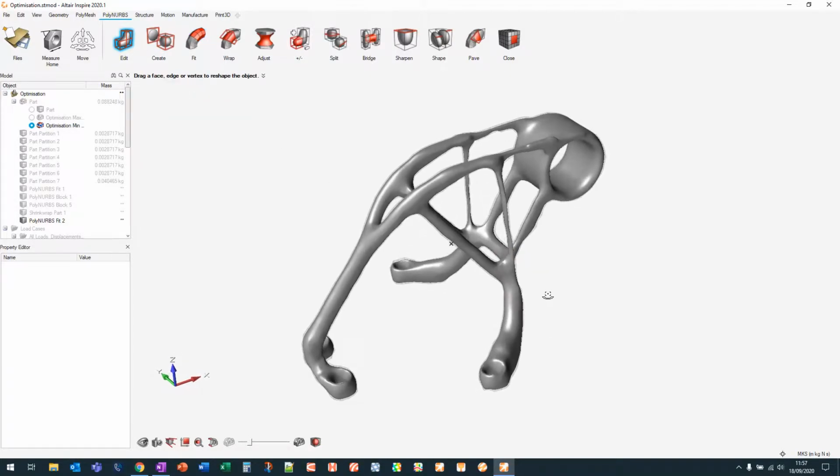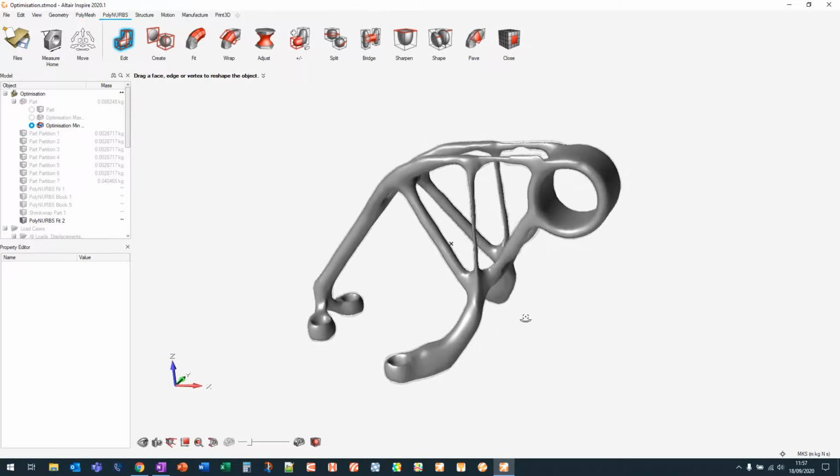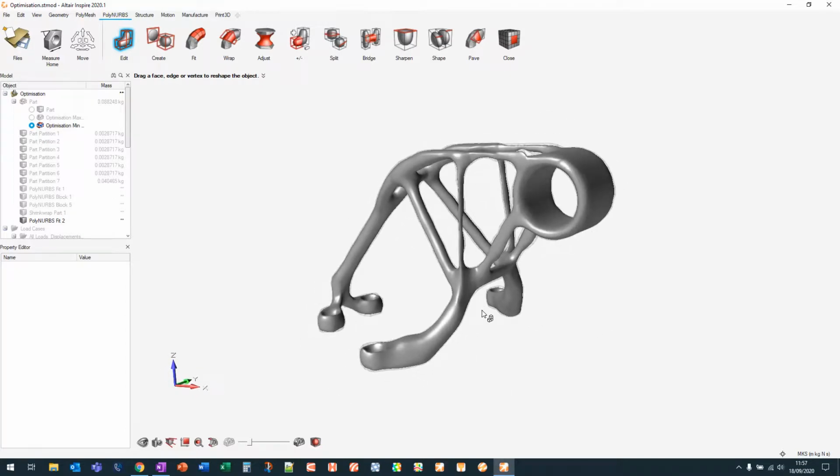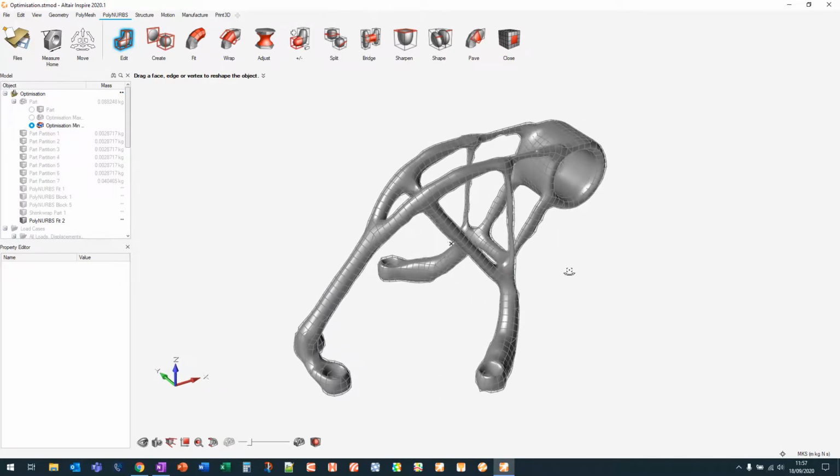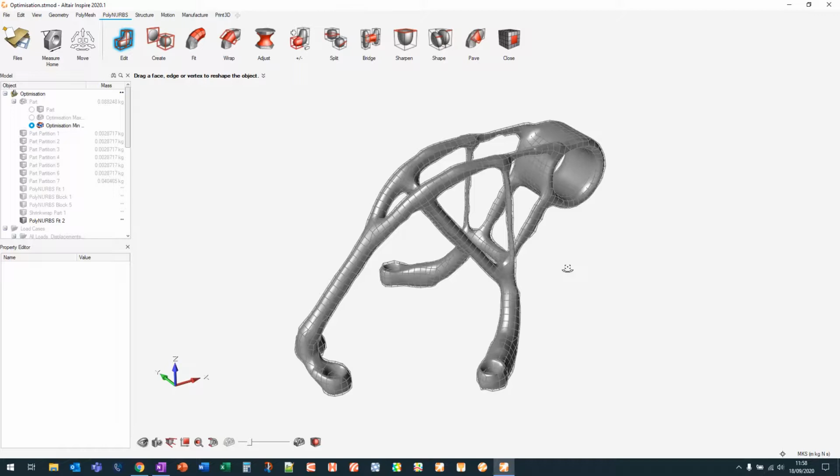So there's a couple of ways in which you can go ahead, optimize a part, and then take something back into CAD. A couple of quick ways, really depending on the complexity of the part. You can either use the wrapping tool, the automatic polynomials fit, or the shrink wrapping. It really depends per use case.